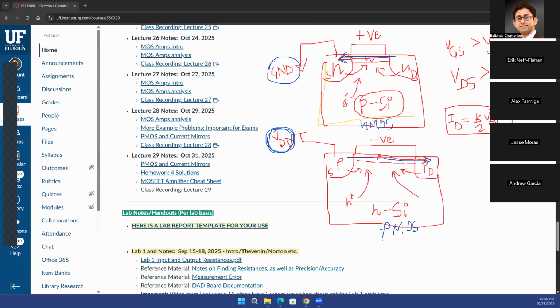And what does that mean? That the channel region was originally a p-type silicon, but you are creating an N-type silicon instead of p-type. So however much concentration of holes you had initially, you want to create the same concentration of electrons in the channel just below the gate to call that I have reached my threshold voltage. So the channel was originally p-type. That means there was a higher concentration of holes. You want to create a higher concentration of electrons, but by the same amount.